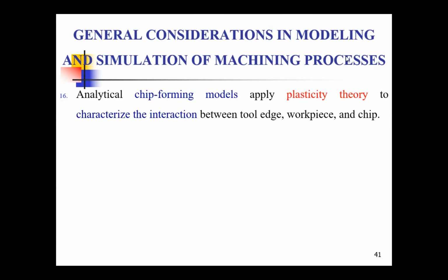So this applies plasticity theory to characterize the interaction between the tool edge, workpiece and chip. There are three interfaces: tool and chip, that is the first one, tool and workpiece, then chip and workpiece. So by using this plasticity theory, we form the chip formation models.